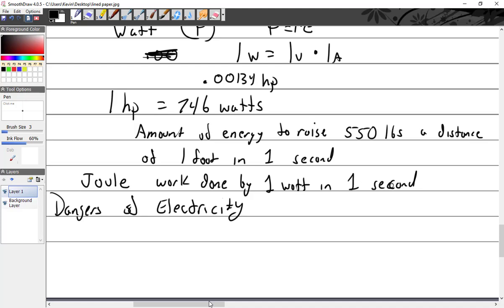Can you guess how much current you put through a crankshaft? A lot. What's a lot? 100 amps? 200 amps? You tell me. Well, in the neighborhood of 3,000 amps. My particular machine was quite lengthy, with a bar across the front. I put the crankshaft in, step on a button, these rams go in and hold it, and then I put the juice on it, flow the fluid across it and lean into it. My knee would hit a bar and energize it.